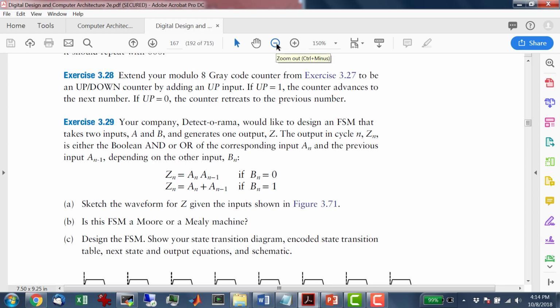So basically, when you do the hardware for this, it's going to look like this. You're going to have a flip-flop with a clock and a reset, and then you're going to have a going in, and this is your state, current state. So this is pretty simple. The current state is literally just the delayed version of a. When I say delayed, it's the registered version. Sometimes they call this the registered version. It's a through a register or a through a flip-flop.